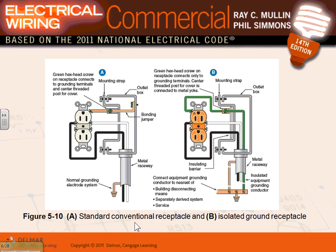I don't know if they make an insulated ground conductor with Romex. This is mostly conduits or MC/AC cable. Guys, if you're dealing with MC cable or AC cable, inside the MC or the AC cable you're going to have two grounds, or the shell will be used as a ground.